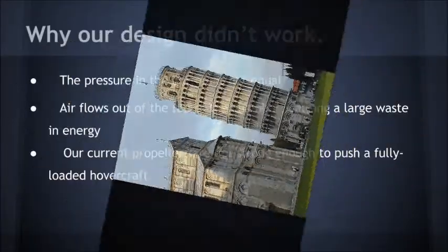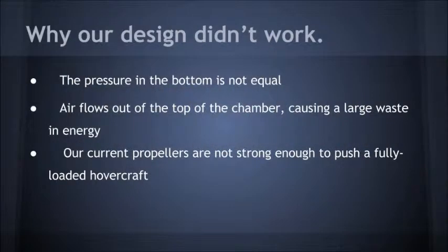Our hovercraft did not move as we intended at FED and barely made it past the starting line. There were 3 issues as to why our hovercraft was unable to complete the required objective. Firstly, the main lift motor was unable to sustain a consistent amount of pressure, which led to some turbulence after continued use. This is because we were unable to develop an efficient enough system to have airflow exit out the skirt, instead of the lift motor's hole.